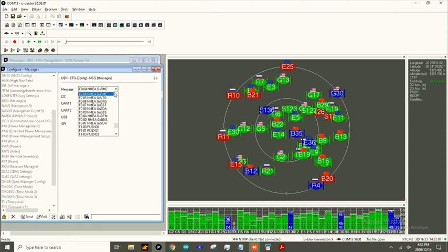And again, this is for our own working iteration or version of the NTRIP Caster. If this can remain enabled, by all means do so, but this is the configuration that we, through trial and error, have found to be working correctly. So the other NMEA messages appear to be disabled, which is correct. And as mentioned before, the RAW-X messages should also be disabled. We already confirmed that.